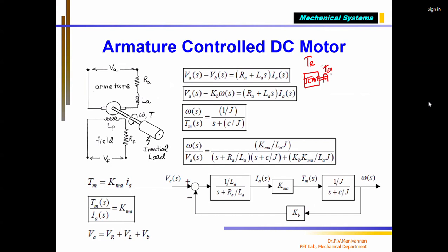So the torque available on this shaft will be lesser than TE. This in turn is given to the gearbox. The gearbox also has friction. Then it is given to the transmission. The transmission system has friction. Then it goes to the differential, correct? Finally, it goes to the axle, to the wheel. So at every stage there is friction.